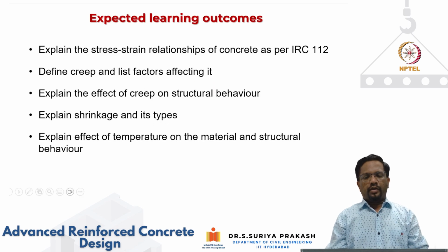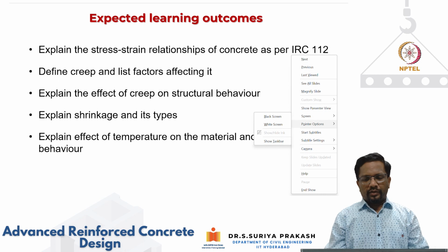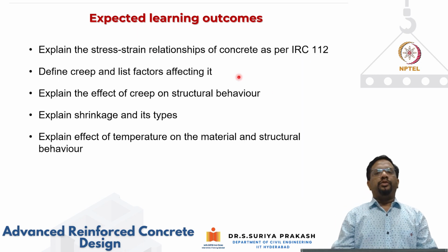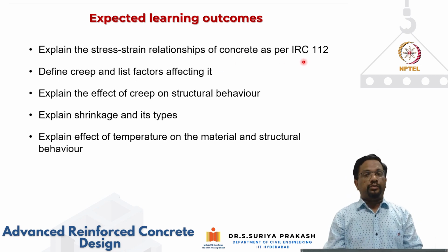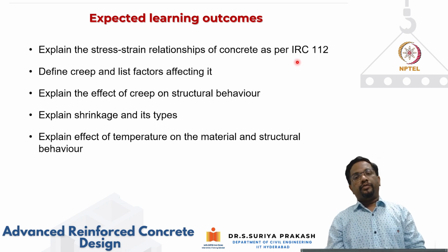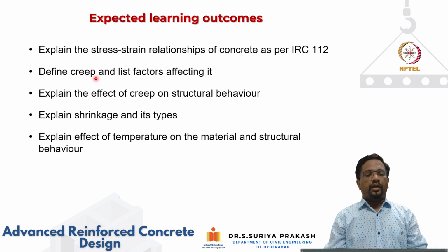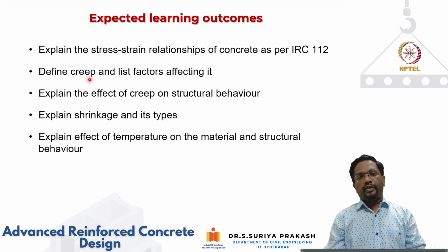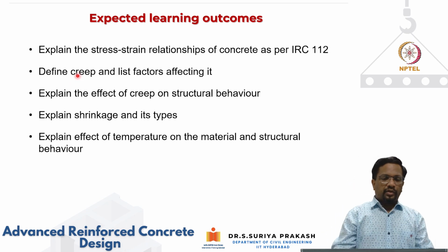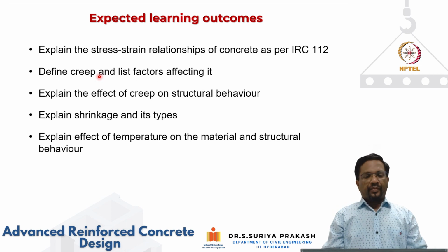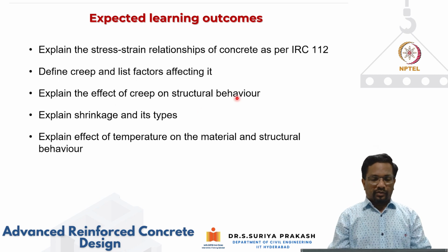After attending this lecture, the student should be able to explain the stress strain relationships of concrete as per the IRC 112 guideline, which is the guideline that we use for bridges in India, and also list out the various mechanisms that affect long-term properties of concrete. Particularly, we are going to focus on creep and shrinkage. So the student should be able to define what is creep and what are the factors that affect creep, and also explain the effect of creep on the structural behavior.